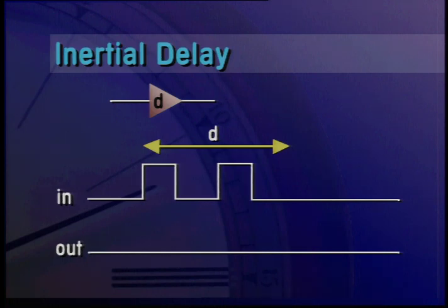When it is scheduled, may be subject to differing interpretations of the inertial model, but there will be only one event which allows the simulator to simply allocate an event block statically and leave it around for all time. We can look at a subtle difference between Verilog and VHDL in this regard.